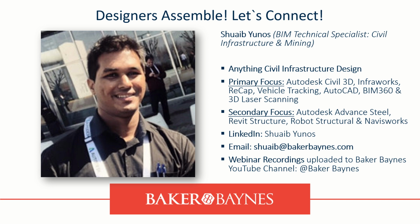Okay, there's one here about the labeling. The question is, are the labeling functions not built into Civil 3D? They are, right? So all those annotates. If you go to your annotate tab in Civil 3D, you will see most of the labeling there. However, most of the styles you will not see there because they are created for the Devotech template.